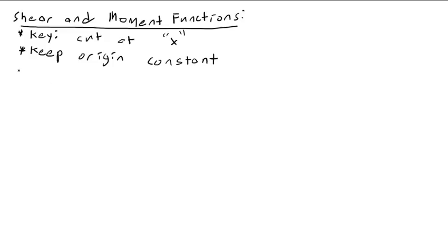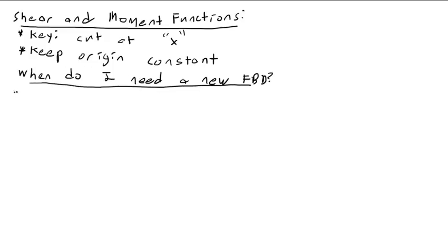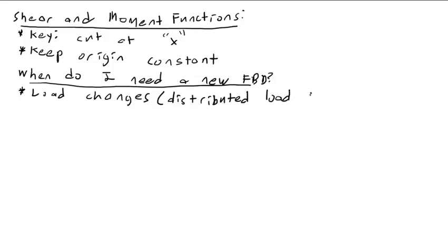Okay? When do I need a new free body diagram? Essentially, when the load changes. Or could be better said as a discontinuity in the load. For example, a distributed load stops or starts.